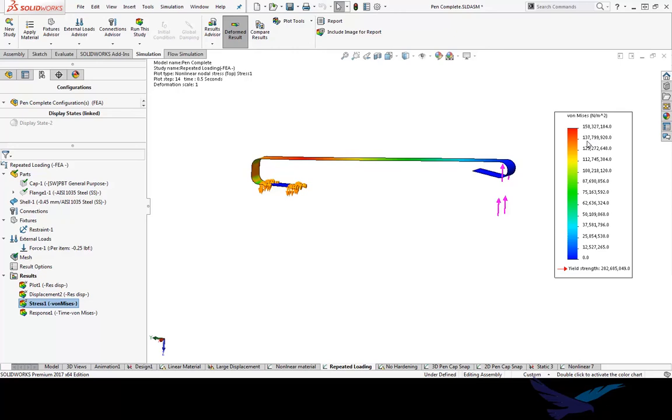So we have full control of how we can apply that load. We can make it faster. We can apply it at just an instant of time and then see what happens. You see that we have that control in terms of lifting that rule that we had initially in linear static. We can now control it with the time domain. All right, so those are the things that we can do in a nonlinear problem.